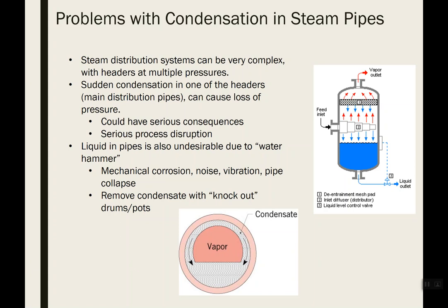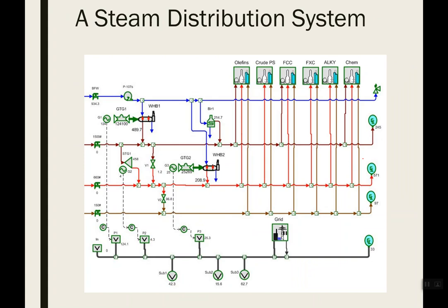So they actively try to knock all those vapors out. And if you have a feed coming in, there's going to be some separators here, maybe even cyclones, and they'll hit some kind of mesh here, and that'll allow the vapor to pass through, but that'll encourage any liquid to form droplets and then drop out of this thing.